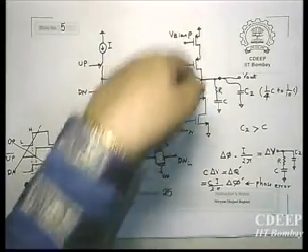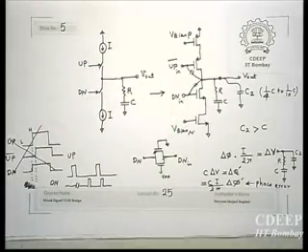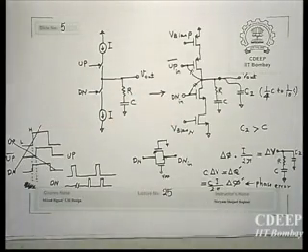But again, if these two are not the same, there will be a continuous source or sink error current giving charge, and this error will continue if the loop stays in for a long time. Automatically it will lead to a change in the frequency of the VCO. It will come back, but if you continue for a long time, you will see that the frequency of the oscillator is reducing and increasing. So you will see some kind of noise around the stable frequency.